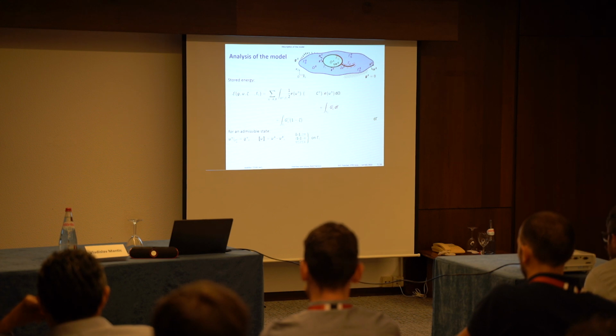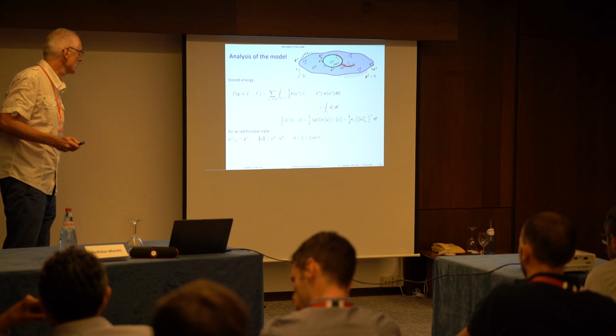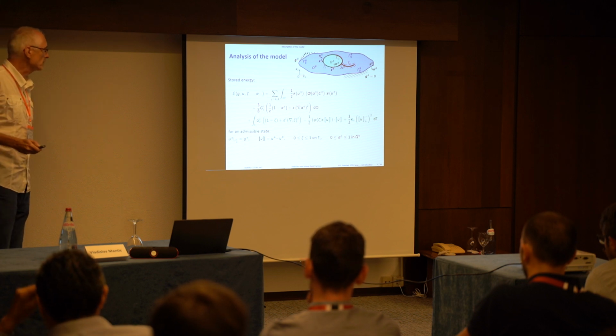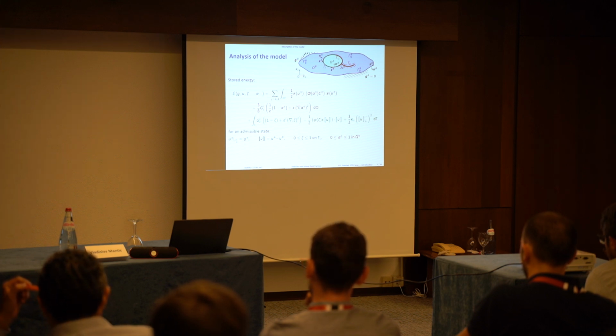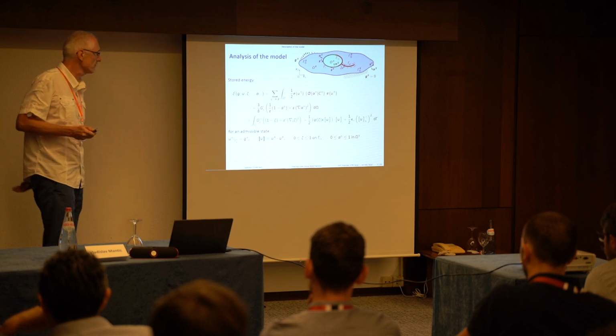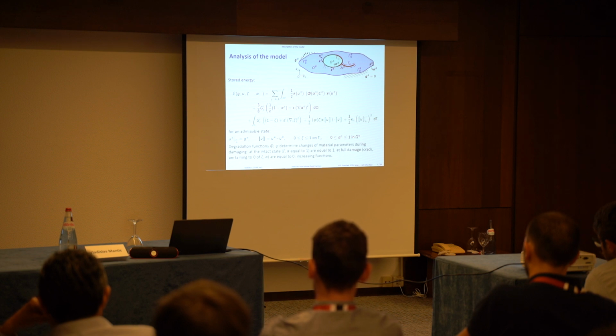Okay, so within the adhesive contact we have a thin adhesive layer which needs some additional energy, and in the same way it works also for the phase field model, so that the energy of the crack is regularized by a very similar function, which is used also in the adhesive contact, and also we have a very similar form of the energy in the bulk or on the interface, which uses some degradation function which characterizes the degradation of the material and arrangement of the actual crack.